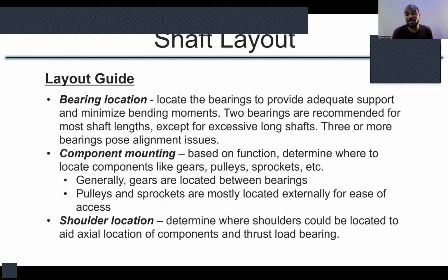For a gear system, because we must lubricate gears, gears are placed between the bearings. So you will have your casing, and then your bearings are usually inside that casing or housing. You locate your bearings there, and then between the bearings, you now have your gears. Is that okay? Between them.